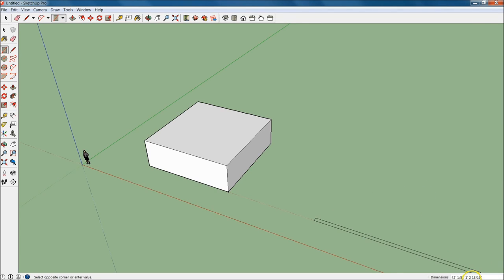And you'll see that these dimensions, how they're formatted, are a little bit different. Let's go ahead and pull this out, and we're going to make a 10 by 10 shed. How this is formatted is it'll take your X and then your Y dimension. You'll see there's that comma right there in between the two. So what we're going to write is 10 feet, comma, 10 feet, and hit enter. And you'll see that it's 10 by 10. Double check it.